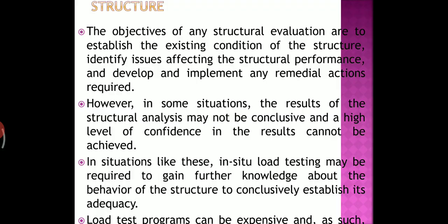So what is the main objective of doing this load test on the structure? The objectives of any structural evaluation are to establish the existing condition of the structure, identify issues affecting the structural performance, and develop and implement any remedial actions required. However, in some situations, the results of the structural analysis may not be conclusive, and a high level of confidence in the results cannot be achieved. In a situation like this, in situ load testing may be required to gain further knowledge about the behavior of the structure.